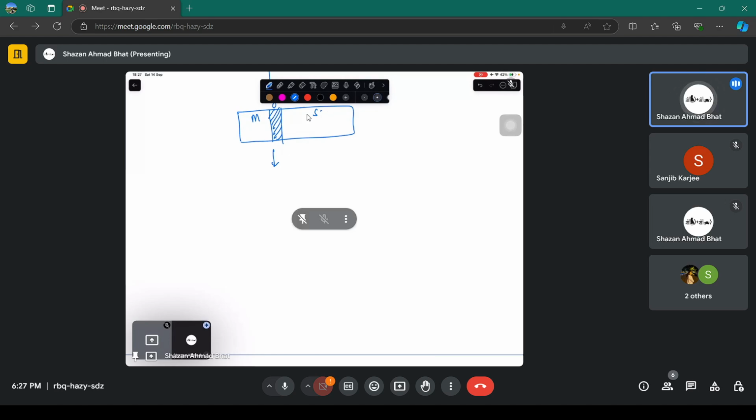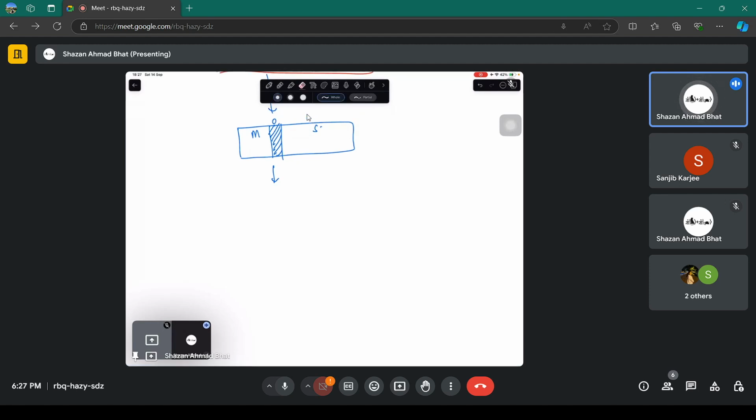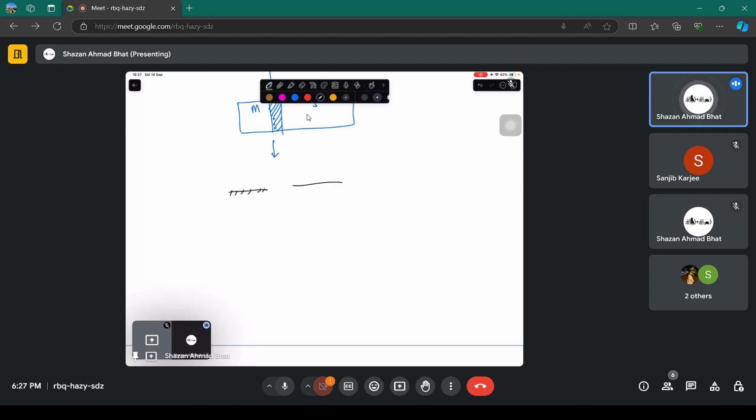Okay, so what you're going to study today is the electrostatics of this particular MOS system. So what happens when you place an oxide? Earlier you had a metal, you had a semiconductor on this particular side. This was the Fermi level of the metal. This was, let's say, the conduction band of the semiconductor. Let me draw it like this. And this was the valence band of the semiconductor. Let's consider this as initially n-type, and this is the Fermi level of the semiconductor on this side.